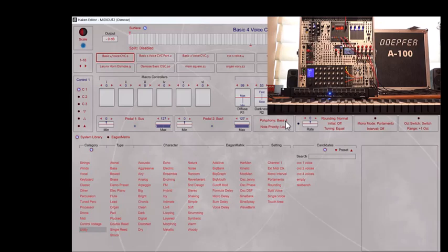You can see the CVC supports up to 4 channels of WXYZ outputs. For the Osmose, that's going to equate to a gate on W, 1 volt per octave pitch, for the most part, on X, your aftertouch on Y, and your pressure on Z. And you can set those various ways. You can also set this to different voltages, either through the editor with preset voltage options, or you can program voltage on it in the matrix as well.